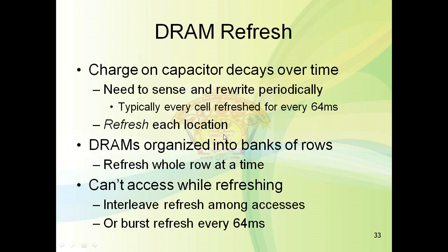These memory cells are arranged in an array. So this array is nothing but one bank, and this bank is recharged or refreshed periodically by row. These are refreshed a whole row at a time of one bank, and then the next bank. Likewise, these cells are refreshed. While refreshing, we can't access the data, meaning we can't read or write.